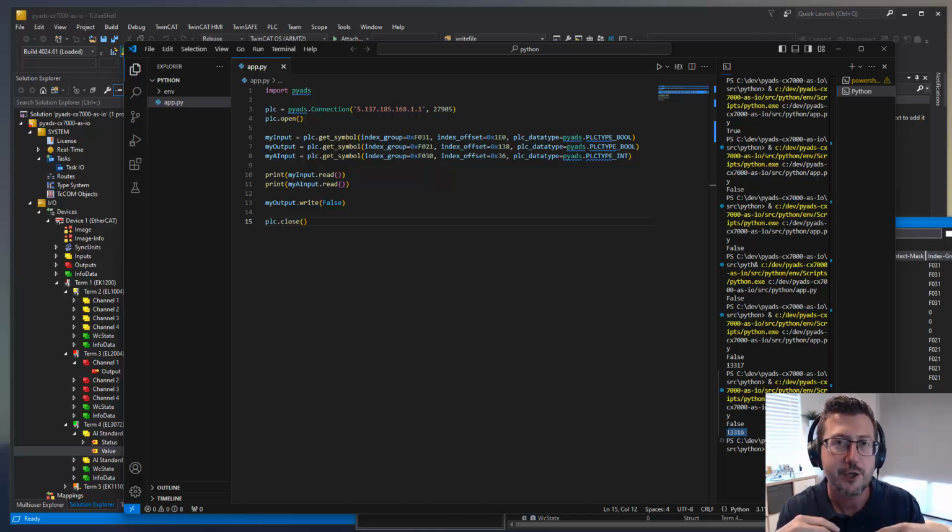But hopefully that can show you that by spinning up an ADS server, disabling the PLC, there is no PLC code in there, spinning up the IO, if that was third-party IO, 100% it can take it. Just remember the CX7000 doesn't support DC clocks, so that you are limited to some of the terminals that you can put on there. But if you need to implement that and you need to pull back, for example,